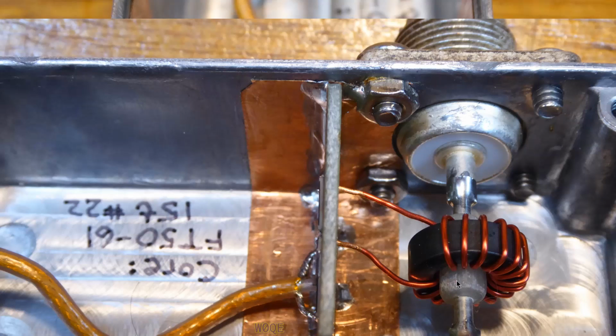The performance I got out of this circuit was quite good. The SWR at 150 megahertz was 1.02 to 1, and this helps. This little bit of inductance in here helps compensate for the SO239 connectors, and I'll go through that in a second here. But this circuit works really pretty nicely. And it's got an SWR, like I said, 1.02 to 1 at 150 megahertz. Its coupling factor at 100 megahertz was 40 dB plus or minus a tenth of a dB. And at 150 megahertz, it was 40 dB plus about 0.3 dB.